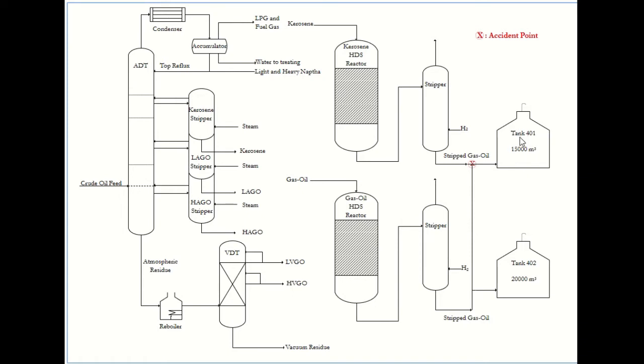And in Ashdod Oil Refinery, the blend in the storage tank included streams from various sources, which are the high and low sulfur gas oil from tank farm, the light atmospheric gas oil, heavy atmospheric gas oil, and the light vacuum gas oil from the crude unit, and also the hydrotreated gas oil from the two treatment units working in parallel on gas oils. And the product produced will be diesel fuels and light heating oil.